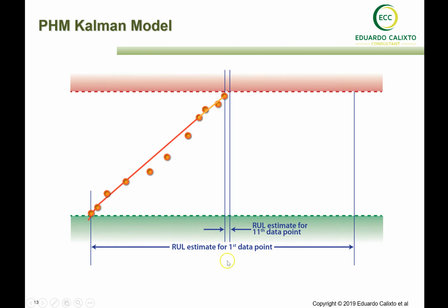Then the advantage of having this model is that I'm aware of that, and that now the remaining life is shorter, almost 50%, because this sensor operated many times at a higher temperature than the operation limit. And then I can make a very accurate inspection now, not in this region as usual as defined in the very beginning, but considering all these effects in the proper time.